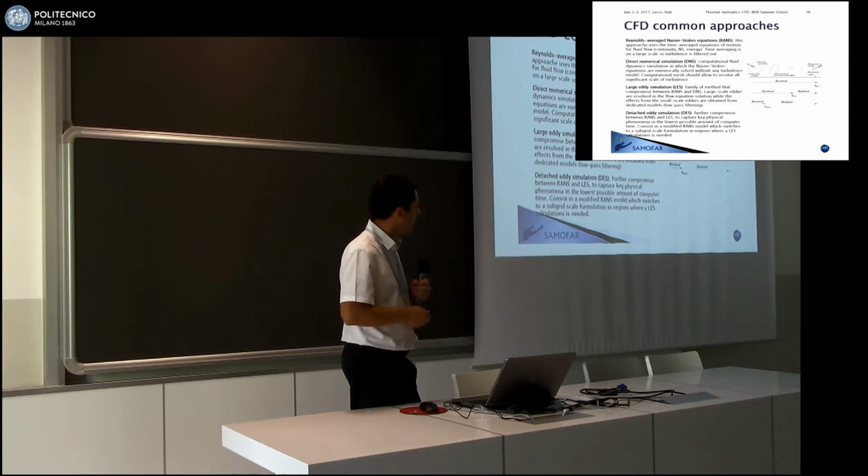Here on the right, you can see a fluid structure. This could be an eddy or a vortex of different size. These are the small ones that will dissipate the energy, as I said before. This is the bigger one that may be occupying the whole pipe. So the idea between these three or four different families is that the RANS method is basically nearly not considering the structure of the big eddies. Maybe if very large, you can see it.